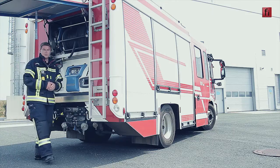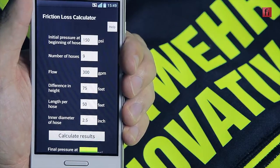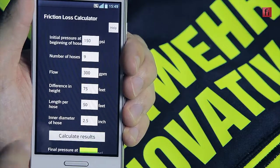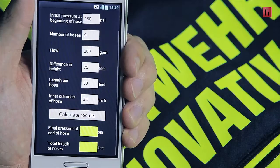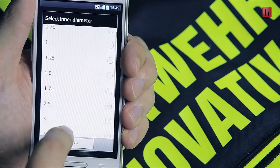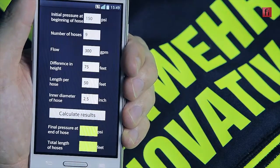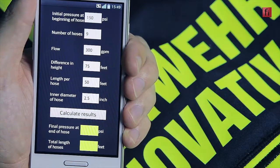The app is flexible and allows you to select other values and different types of hoses. When using metric units, the calculation is done for the stored hose coupling system, according to DIN 14811. When using US units, you can select the size in inches. The calculation is done according to the US NFPA hose friction loss standards.